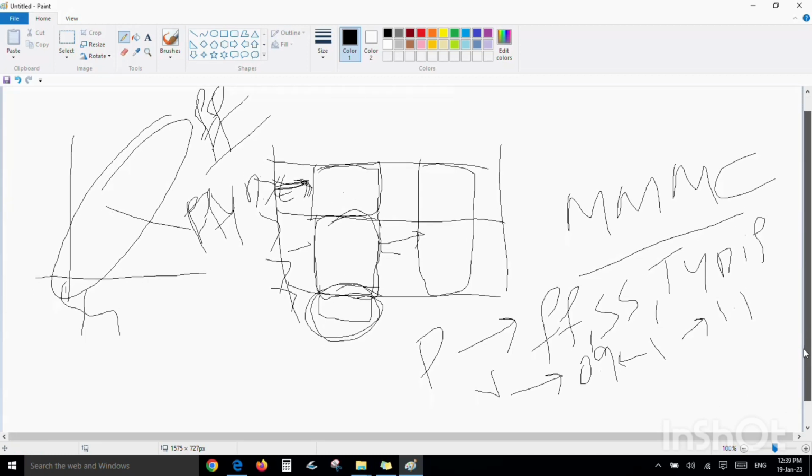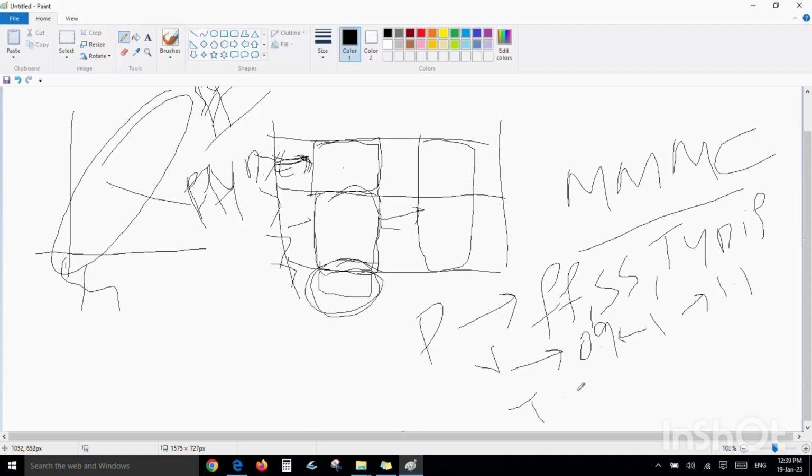After that, temperature depends upon the specification. Minus 45 degrees to 125 degrees we used to take. All these corners I need to close the timing, so that my chip can operate at any corner or any point of time. That is what I need to take care of.